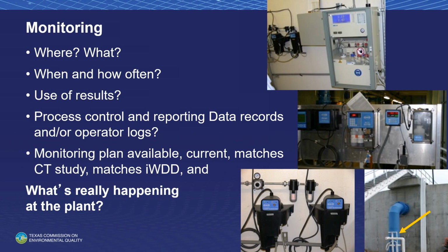Monitoring plans should be up to date. CT studies should be up to date. Operator logs. You really ought to keep a good operator log. They're invaluable. What's actually happening in the plant? You know, that's very important. Again, it's not necessarily something that's a regulatory issue, but it's certainly something that if I were running a plant, I'd want operators to do for me so that I could tell what's actually happening with my facility.